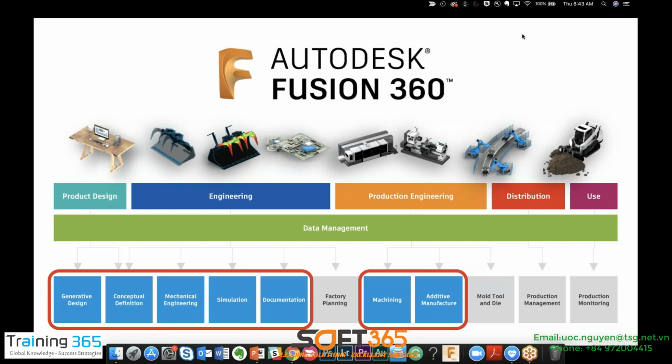And then there is also in there today the ability to spit out 3-axis and 5-axis output. So if you are a machine shop that only has a 3-axis mill, generative can actually incorporate that. And then the last thing is that it gives you a solid model, not just some kind of mesh model, and that can be edited with T-splines. So yes, that was just what I wanted to share about generative.